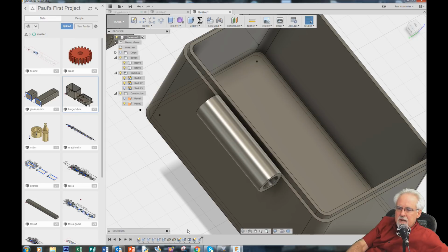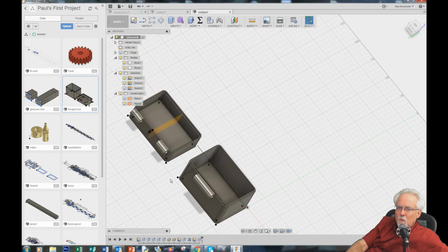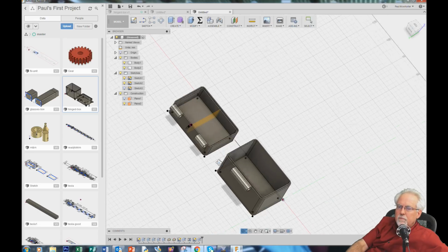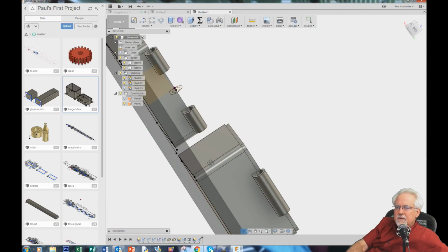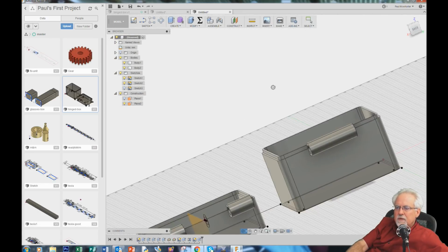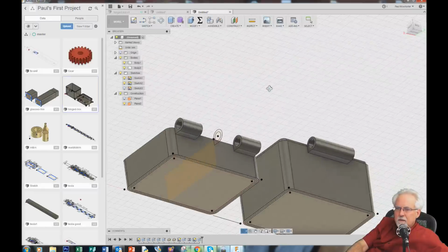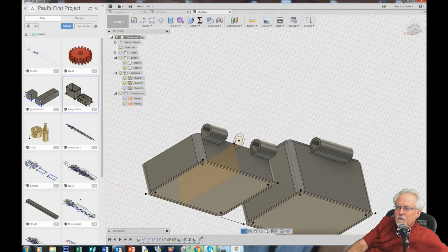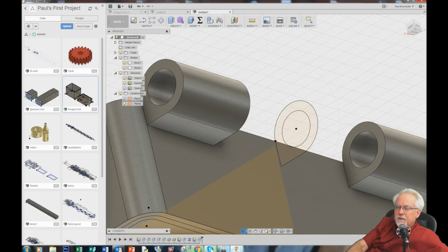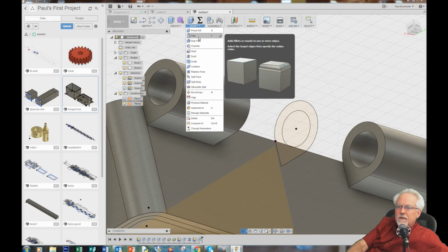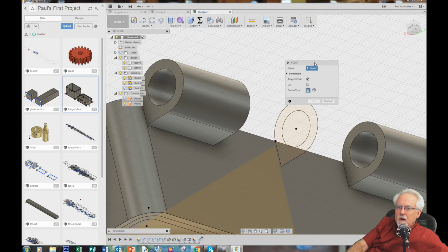All right, so now let's rotate this around. Wow, look at that. This is an excellent parametric design. One couple of real quick bookkeeping things here. If we look underneath here, sometimes the rotate tool breaks my heart. There it is. Do you see how it'd be nice to round that off right there a little bit? So let's get the modify and create a 3D fillet there. And what I want to modify is that.